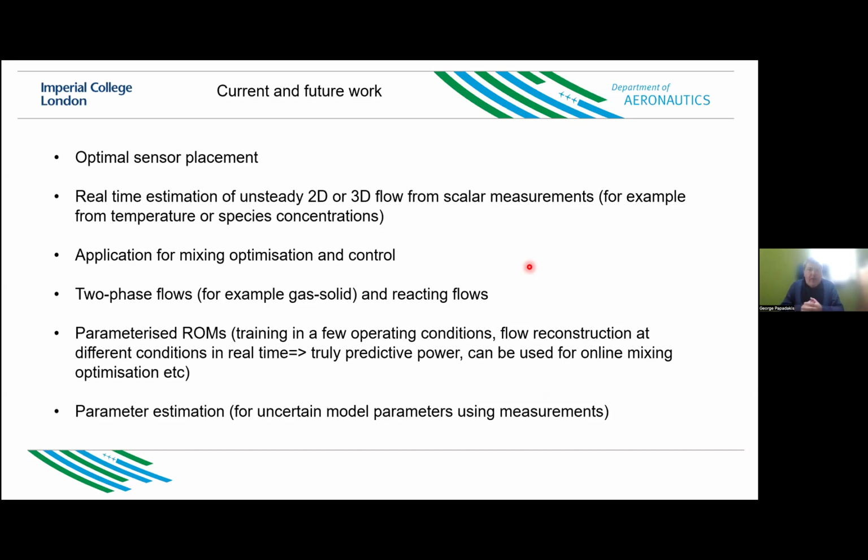So one can do all the analysis theoretically, computationally, and then merge with true experimental measurement, and then, of course, study accuracy, etc. Many questions remain. What is the optimal sensor placement? Here we have used an intuitive method. We have looked at the location of maximum TKE, and this is where we put the sensor. If we put many sensors, is this always the best place? It makes intuitive sense, but this is something we need to look at.